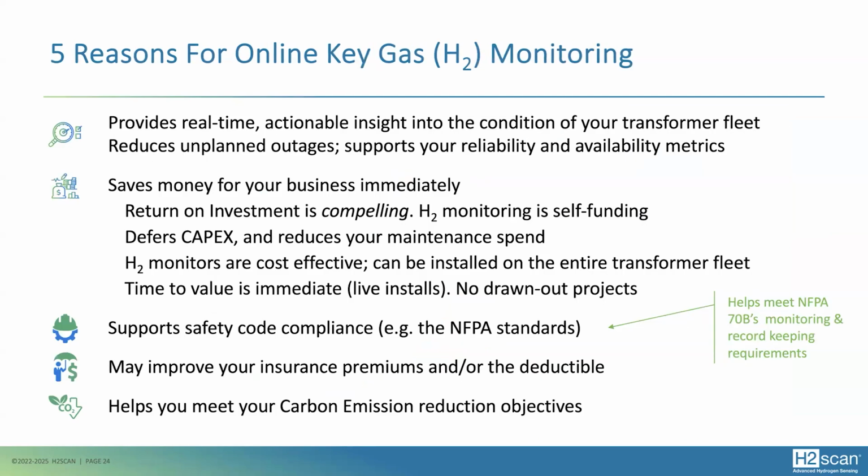So I'm going to start summarizing a little bit for you. Why do you want to do online key gas monitoring as opposed to what we're doing today? The first thing is that it's near real time. It's actionable insight into the condition of a transformer fleet. We see online key gas monitors as part of fleet monitoring, not an instrument to determine the state of a single transformer. For that, a permanently installed multi-gas or a portable multi-gas would do the job. Online key gas monitors are really part of fleet monitoring. They're meant to be there perpetually.